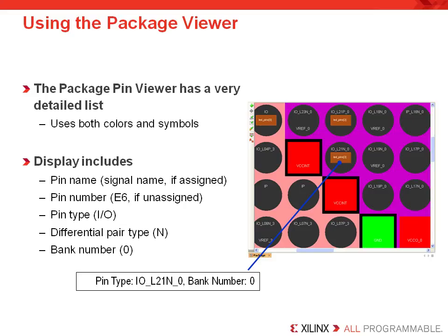The role of the device view and package view is pretty obvious, but the package pin properties box allows you to modify the associated pin attributes by modifying the associated text. So we can modify the location, slew rate, I/O standard, differential pairing, etc. with the text box rather than drag and drop it to whatever location we want. The different types of pins are also given their own shape, so that the available differential pairs are shown with a hexagon, and each is labeled so finding the associated pair is easy. Likewise, unused pins, that is VCC and ground pins, are all labeled and easily found.